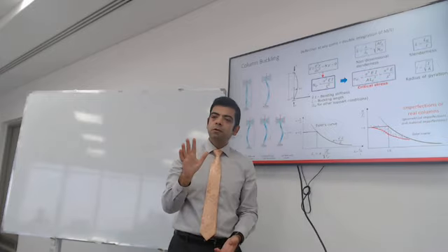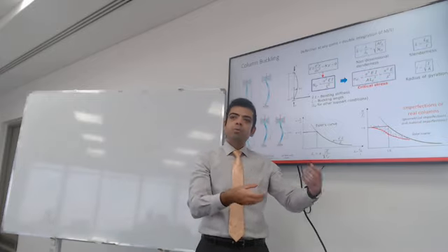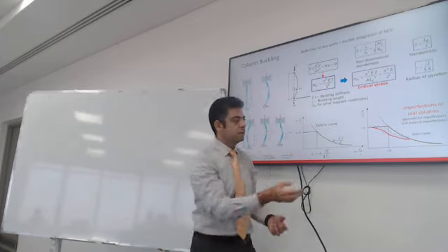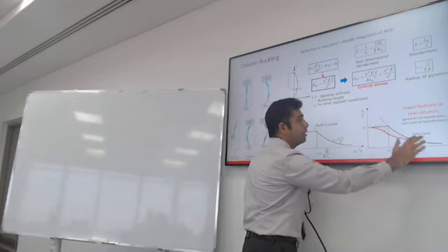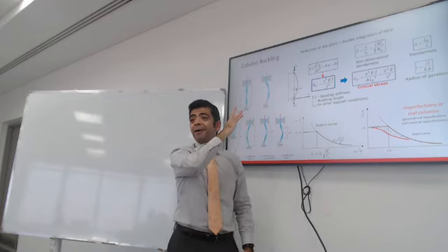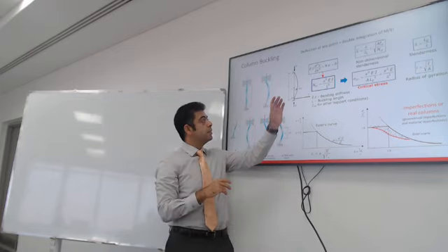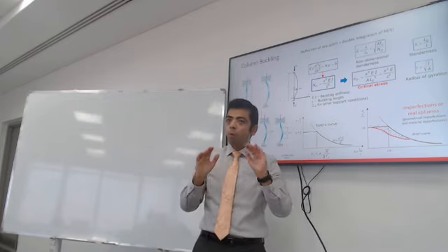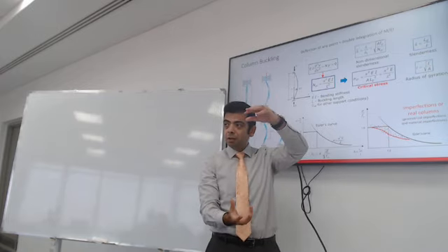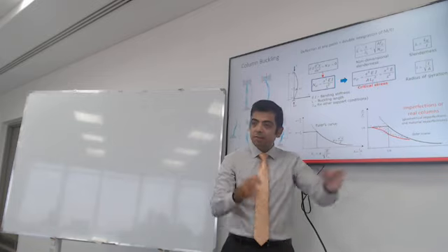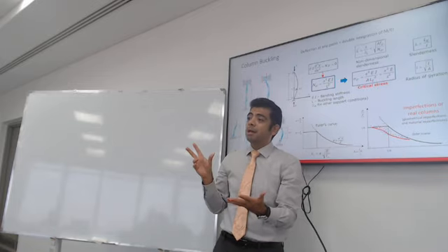So my question to you is, why are the actual experimental results lower than the theoretical perfect equations from the Euler load? Why is there a difference between reality, real columns, and the equations from the theoretical pure mathematics?